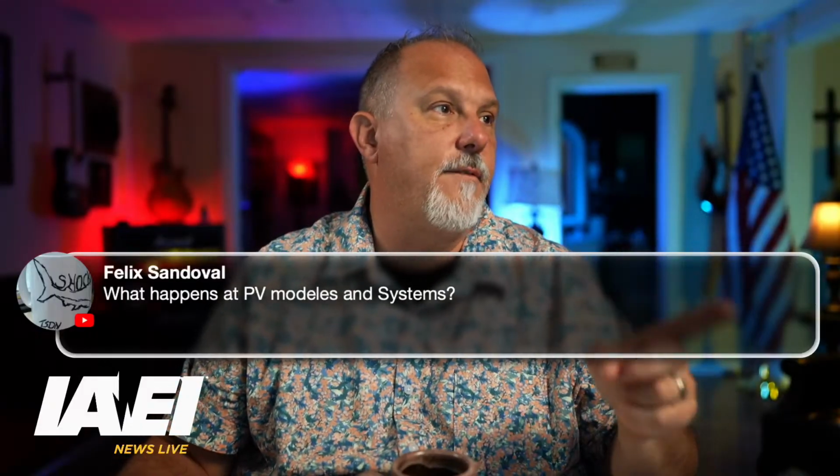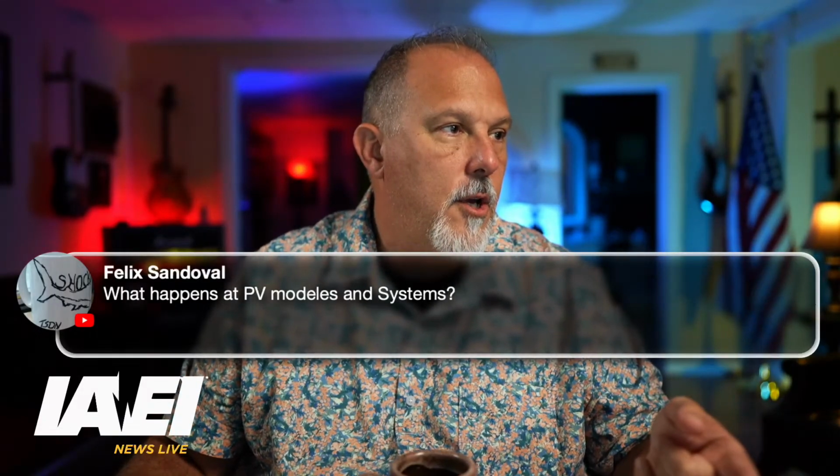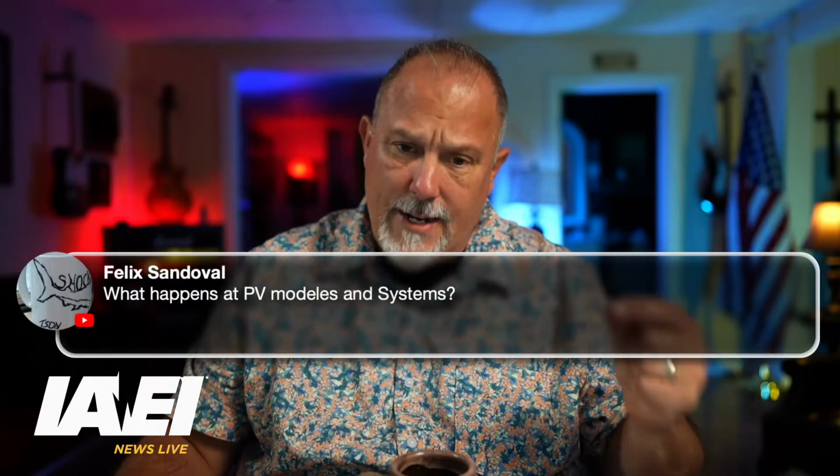All right, so 240.4. Let's go back to 240.4. We digressed. All right, so 240.4 is protection of conductors, and it says that conductors other than flexible cords and flexible cables shall be protected against overcurrent in accordance with their ampacities specified in 310.14, unless otherwise permitted or required in 240.4(A) through (H). So 310.14 talks about the ampacity of a conductor.